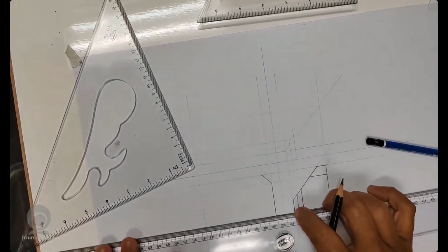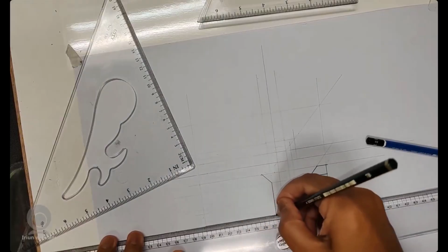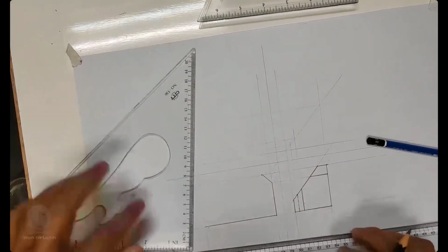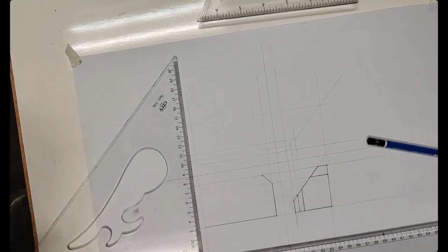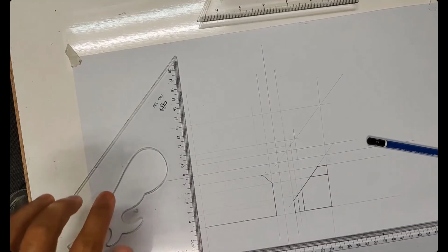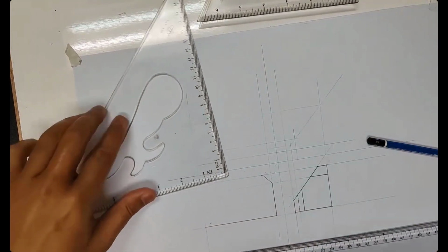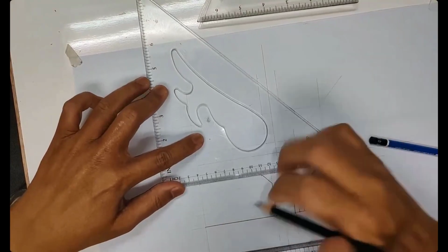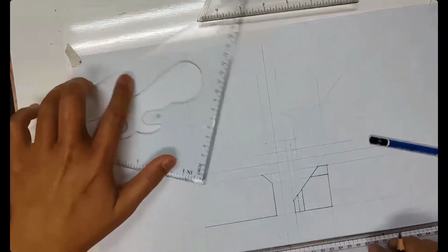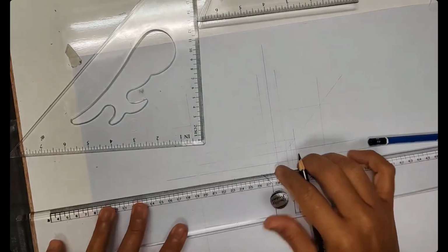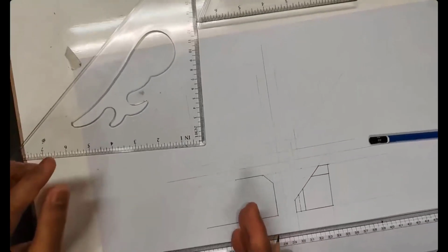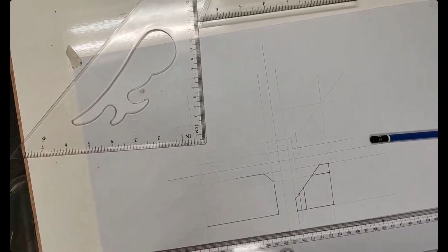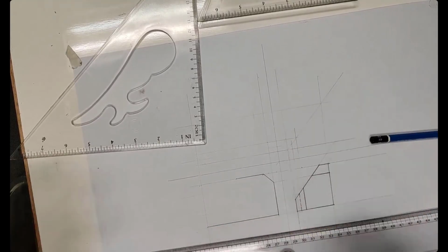Whatever you confirm is the finishing line, outline it with 7B, because too many extension lines will get you confused. Now I have a 10 there. So I have a 30. Can you see the 30 there? This is a 30 measured from here, 1, 2, 3. So I have leveled up until that. Outline it. You already confirm this will be the finishing line, do it with 7B. So now I have a 10 there, and this will be the outline of the front view.